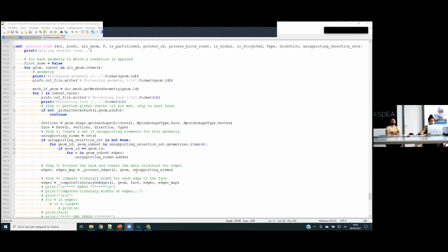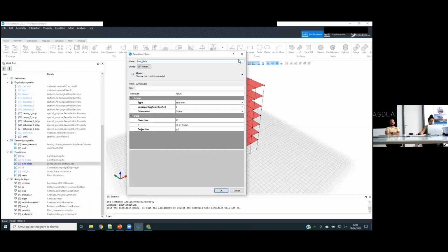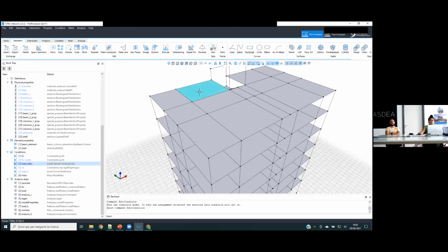Okay. In this case, the surface load is just for you not to have to calculate by hand all the edge loads in each of your frame elements if you have a large 3D structure. But of course, in this case that I showed you, you will not be able to discretize your structure. If you want to create a finer mesh, for whatever reason, you cannot do it because you will then have some nodes that are, for example, in the middle of the slab, and I have not assigned any elements to them, and they will not know how to behave. So instead, you have to mesh it if you want to use the shell approach.